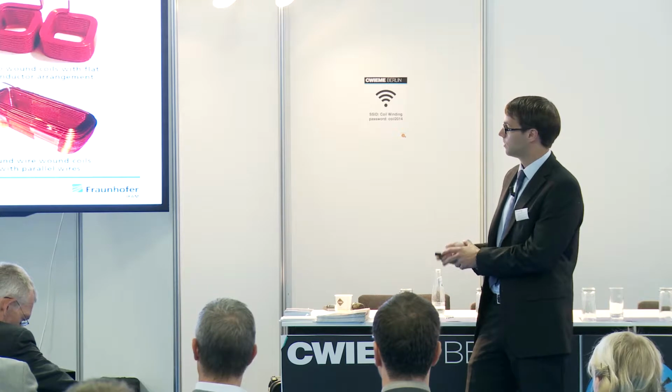So to us, it became clear that there are limits on the current winding technologies. We are limited in slot filling factor to about 60%. And there are, of course, different technologies in winding. On the one hand, the edge-wound coils we see on the upper side. They offer very good thermal behavior and very low current displacement effects, but they have a relatively large bending radius, so you have an increased axial length of the machine and local thinning through the bending process.